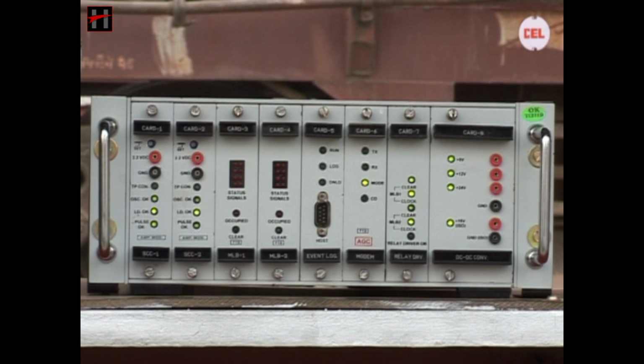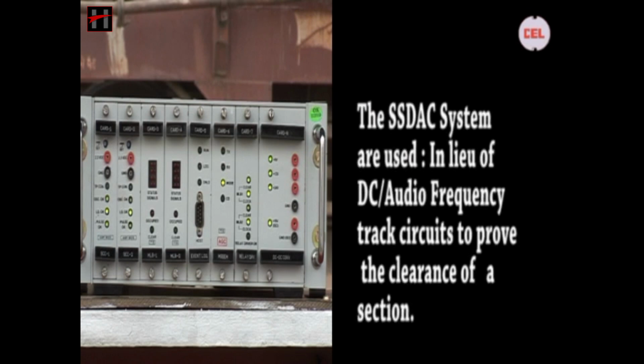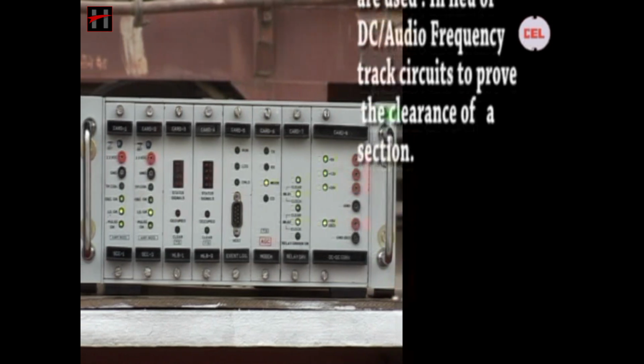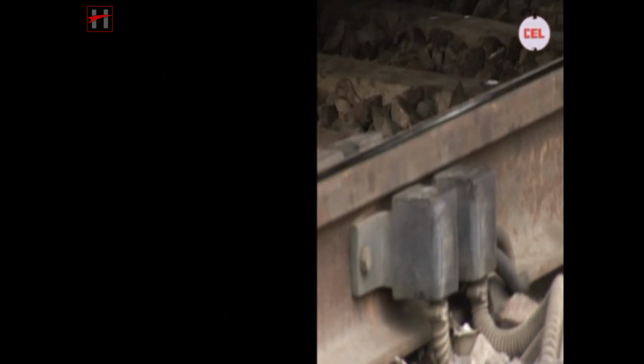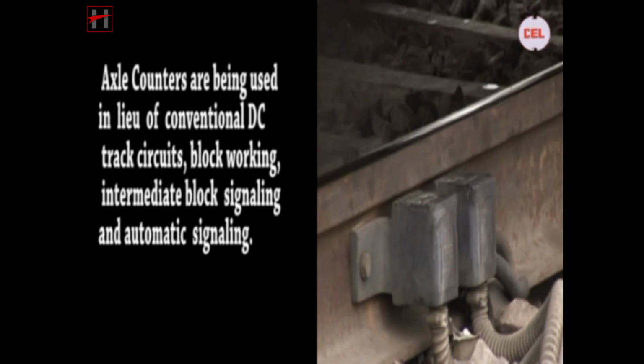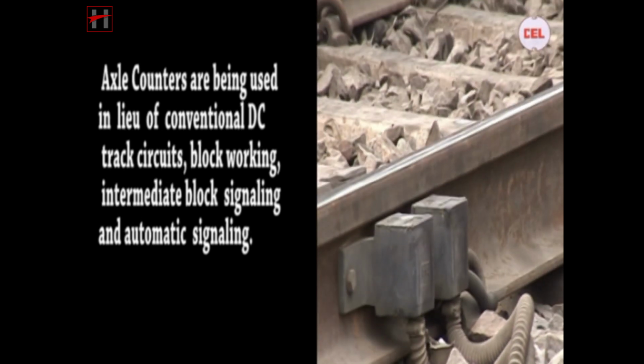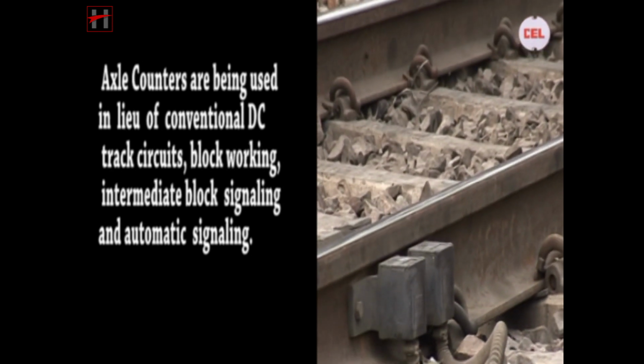The uses of a single section digital axle counter are as follows. The single section axle counter systems are used in lieu of DC or audio frequency track circuits to prove the clearance of a section. Axle counters are being used in lieu of conventional DC track circuits, block working, intermediate block signaling and automatic signaling.